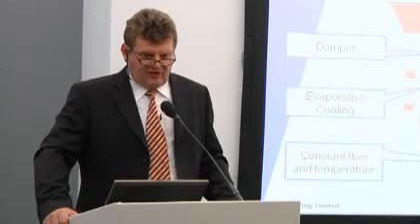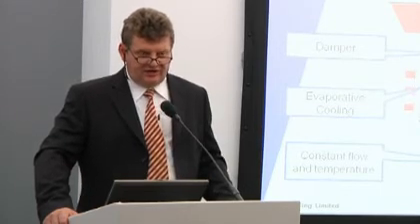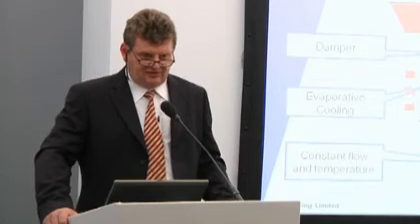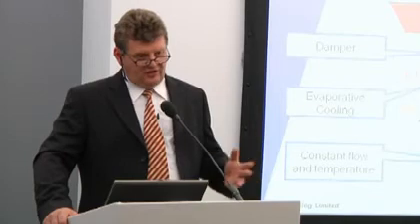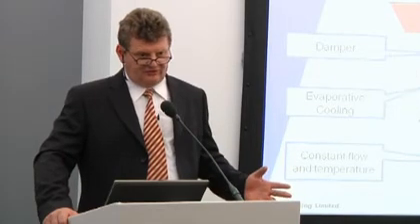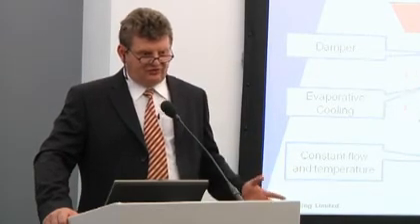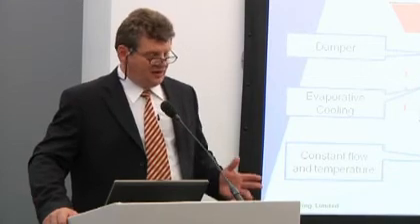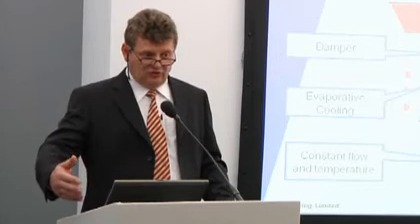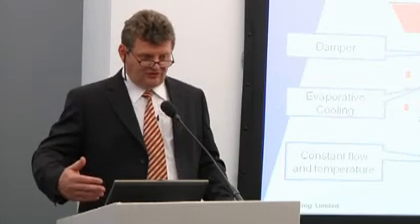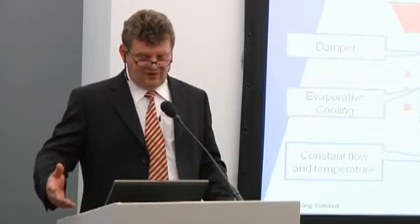As time's progressed, we've actually reduced that, and it's now running at 17 degrees centigrade. The net result of that is, whilst we're achieving the cooling savings, we actually reduce the net IT load as well by running the servers at a lower temperature. So the PUE looked good, but also the net use of the IT went down as well.